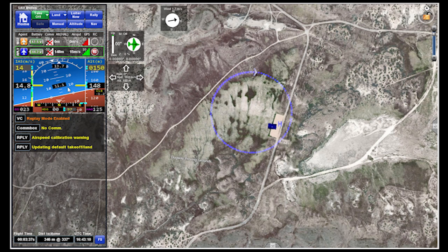And this window is the heading and attitude window, so we can see the attitude of the UAV. The next window is called the message window. We can see if there is no comm, or we lost GPS, or the altitude is too low, so there will be warnings showing up in this window. The last line is the pre-flight tools, so we can zero pressure on every sensor, etc.